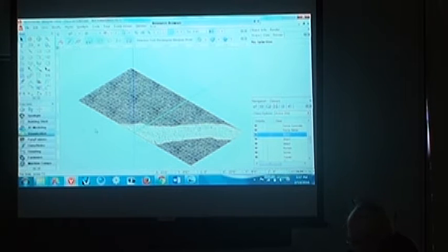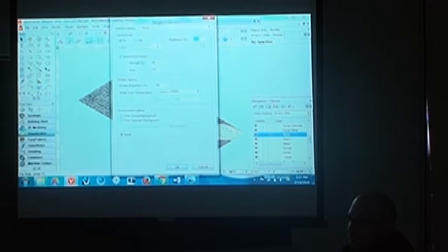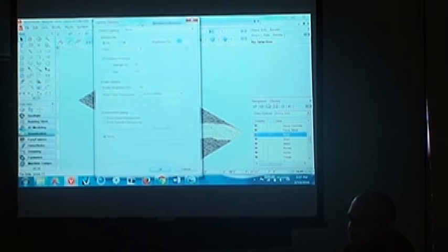And then you're going to want to visualize the texture and see what it actually looks like under some different render modes. So if you go to View, Set Lighting Options, you can make some adjustments here for your rendering purposes. You want to turn indirect lighting off. That's going to make your rendering go a lot faster.